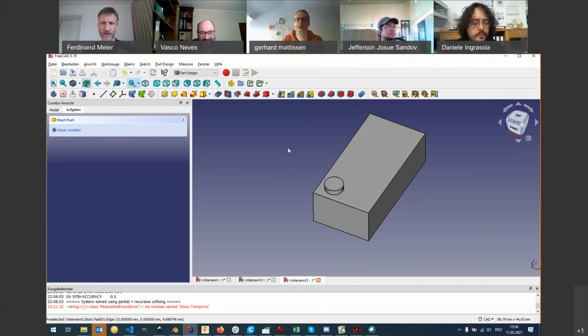One important thing that I completely forgot, which is the 3D navigation. FreeCAD copied the 3D navigation from CATIA, which is actually my favorite way of 3D navigation, because in most programs you use your mouse buttons in conjunction with Shift or Control or Alt. In some programs you don't need the keys, but then you mostly don't have a right click. CATIA implemented this 3D navigation where you only need the mouse.